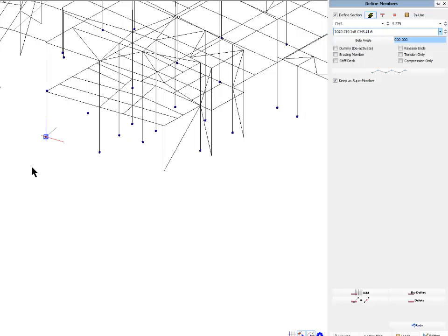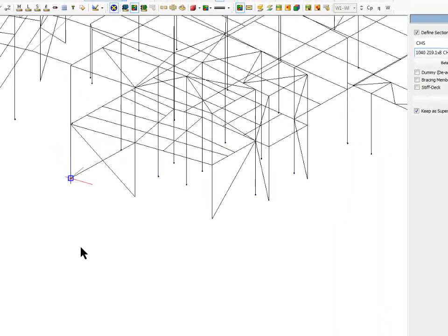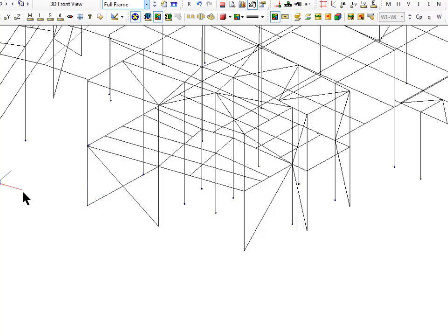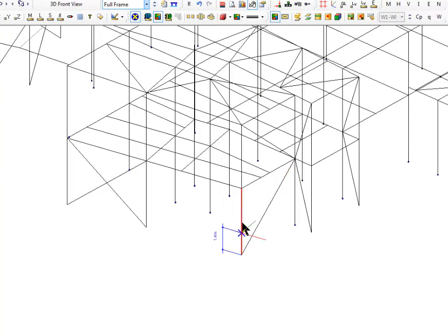And as you can see, I can snap, and then I can go to another member and do the same again. I also have the full tools to create members along a member, so I can say I want to move up 2.1 meters because I'm snapping at 100 millimeters, or 2.2 if I want, or anything else. See, coming down and up and down, and I'm going to say no, I want to snap up